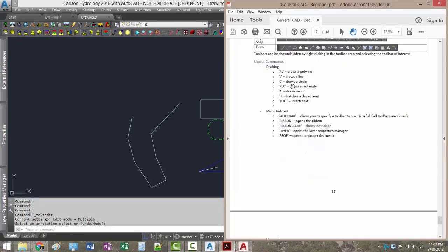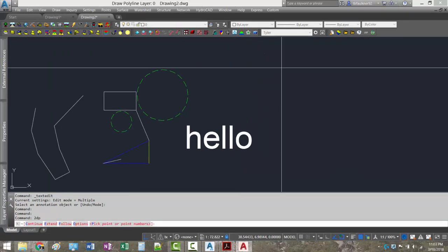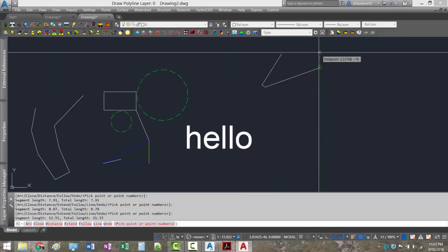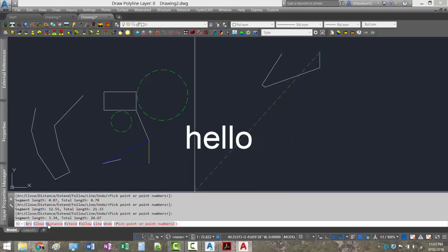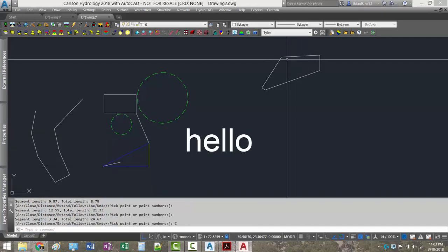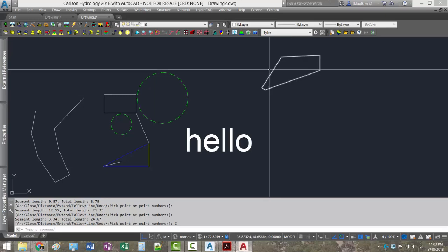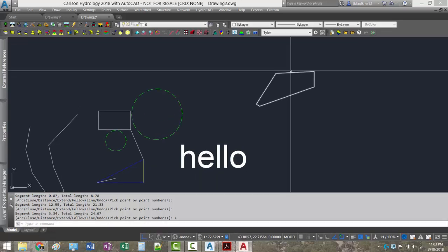The other common drafting tool we use is called a hatch. And to do this, I'm going to draw another 2D polyline. And instead of just pressing enter to finish this off, notice I have a few options shown down here. If I hit Close, it closes that polyline up, and it's like a watertight seal, if you will. There's absolutely no space between any of these segments. With that, I can hatch this in.